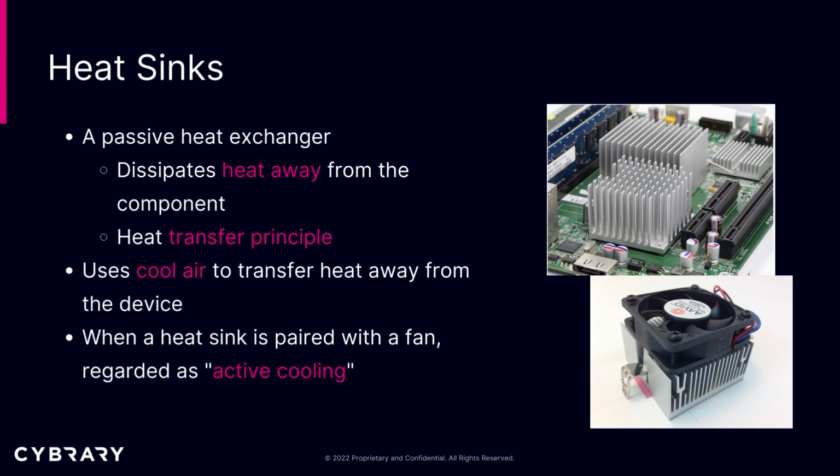Heat sinks. A heat sink is considered a passive heat exchanger. It dissipates heat away from a component, and it's based on the heat transfer principle. Basically, it uses cool air to transfer heat away from the device. Now, when a heat sink is paired with a fan, it's regarded as an active cooling solution.